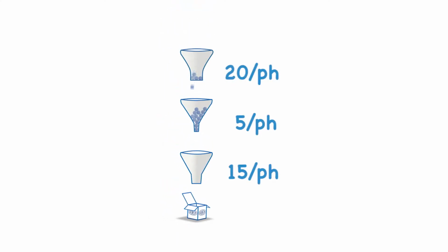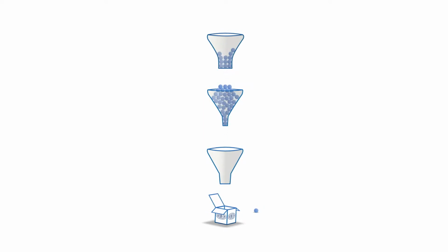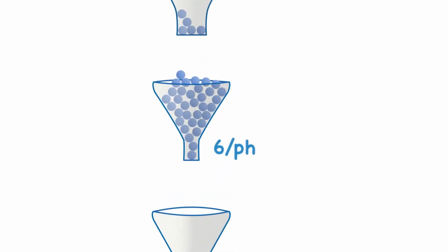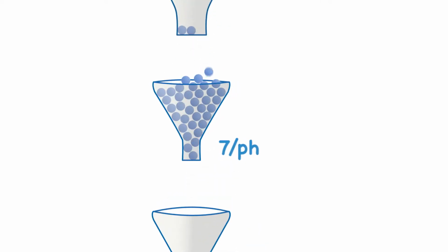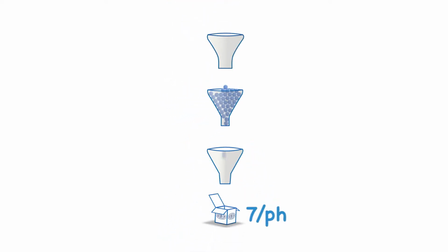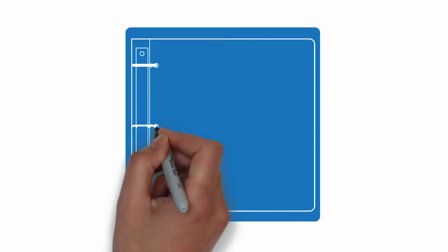So if you have all these machines lined up, one after the other, they will only produce parts as a group as fast as the slowest component. So what's going to drop out the bottom after the third machine is only going to be at the rate of 5 parts per hour. And we can see the constraint sits clearly in the second funnel, where things are backing up. And that gets messy, and that's not good. And the important thing for us is not to overrun the constraint, but instead to help expand the width of the funnel at the constraint. Because if we expand the capacity of the constraint, overall output goes up. Right, and we get our products out faster and keep our customers happy.